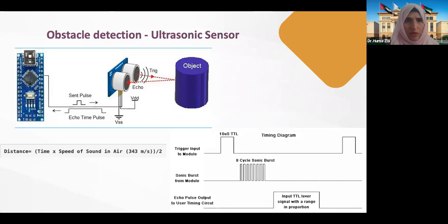We know the speed of sound, the time is returned by this mechanism, and you calculate the distance. So velocity is there, time is there, you find out the distance. And obviously that distance is divided by 2 because you're thinking about distance going forward to the obstacle and then coming back. So actually, this is what is being shown here.